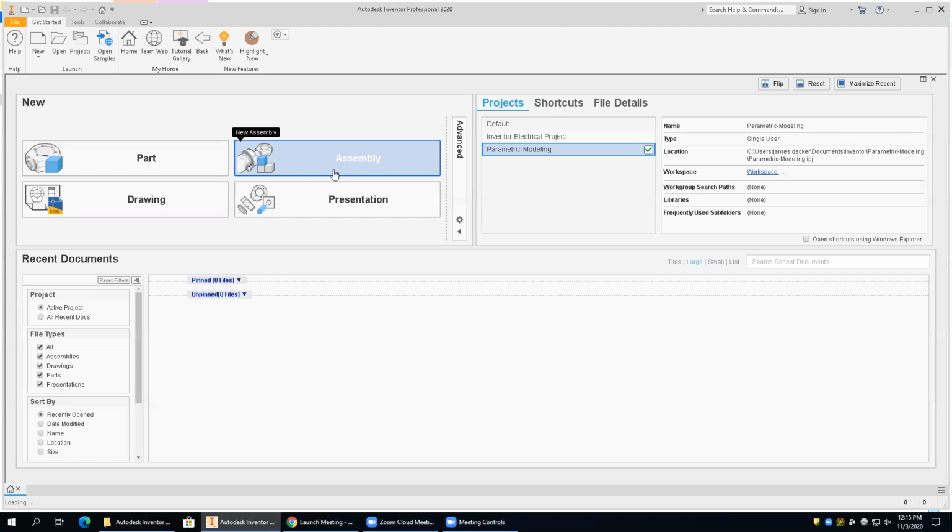And then when you print this thing out, notice there's a drawing, and that's a DWG file, okay? So it's just an AutoCAD drawing file. Basically, that's going to put you in paper space, okay? Now, they don't call it that, but that's what it's going to be, essentially. And it's going to create viewports and all of this stuff. You're going to import your model, but it's a whole lot simpler. But having gone through that process, you're going to see that that's true.